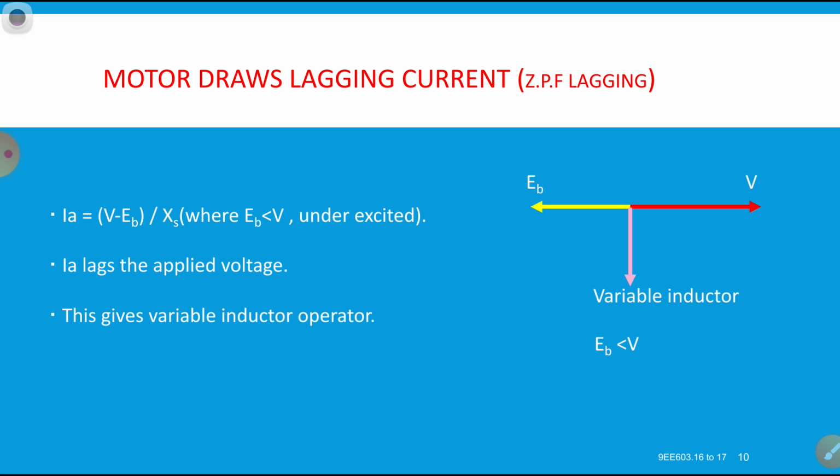As we know, under normal conditions nearly 75% of the load in our power system is induction motors and heating furnaces. So, these try to draw reactive power from the supply. Then the total overall power factor is a lagging power factor. Then what will happen? In our substation, to improve the terminal voltage in the line, we are going to use the OLTC, on-load tap changer. By changing the tap, we are going to increase the terminal voltage.